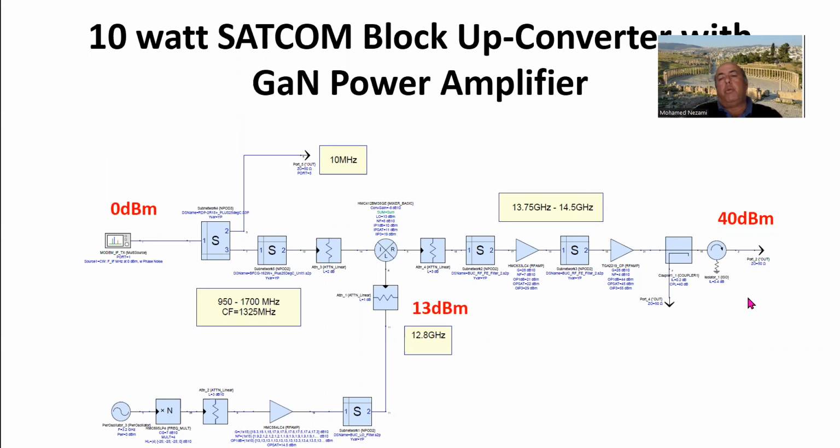And then to protect the whole system from reflections from the antenna feed, we put this circulator. And this is important, not just protection, because once you assemble this in the field, nothing can come in there unless, of course, a bird would land on the horn antenna, or somebody puts their hand, or the antenna collapses down from wind.